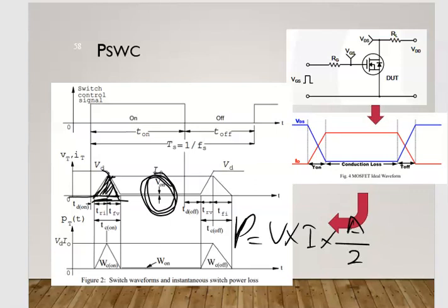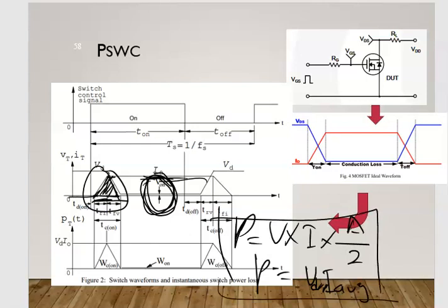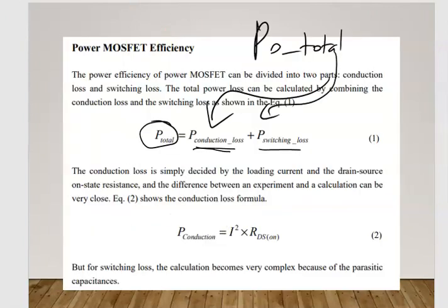Okay, this is the amount of your switching loss, whereby your conduction loss happens during the conduction, P equal to V drop times the amount of current passing through your circuit, average or RMS. So this is what you have to consider for the switching and your conduction loss. So let's take a look again at the slide.